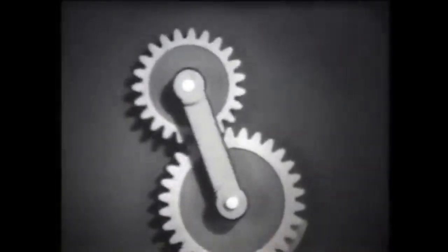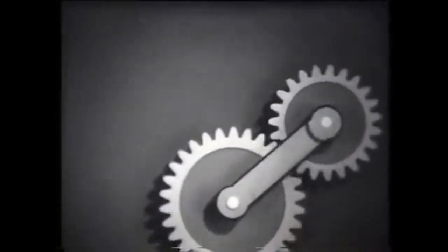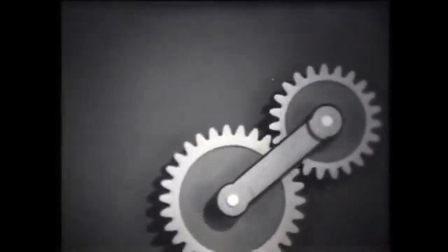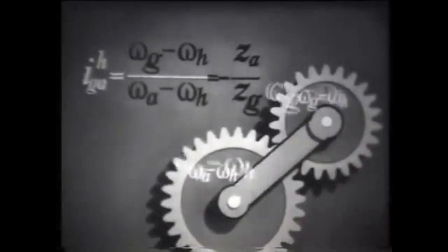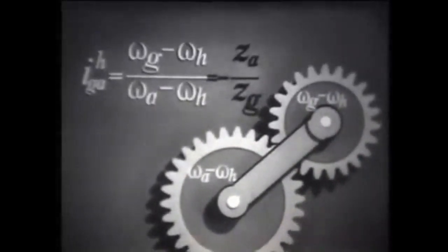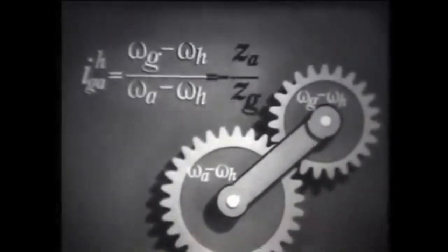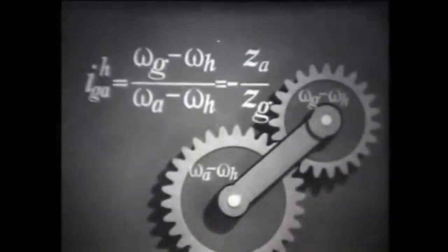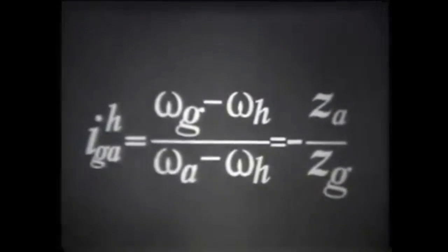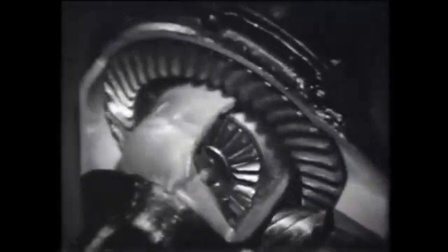The gear ratio of planetary gears is determined by the method of motion reversal. When the carrier is stopped, it is equal to the ratio of the angular velocities of the central wheels, taking into account the speed of the reversed movement. Planetary mechanisms with two or more leading links are called differential.